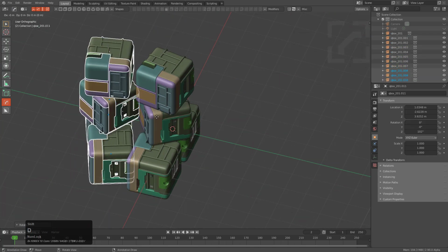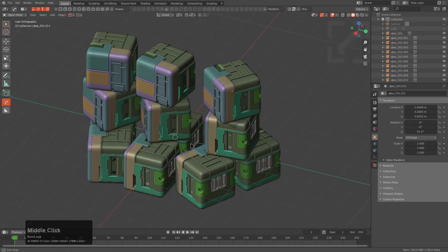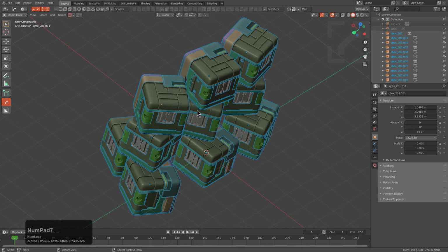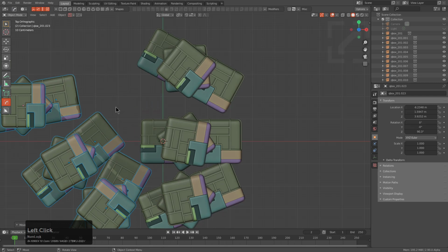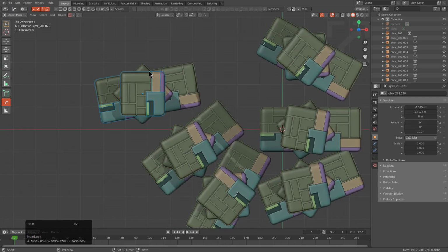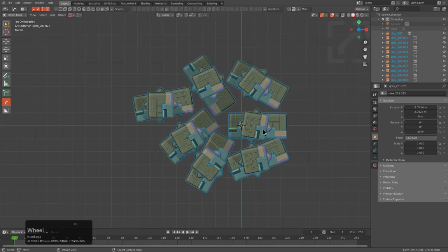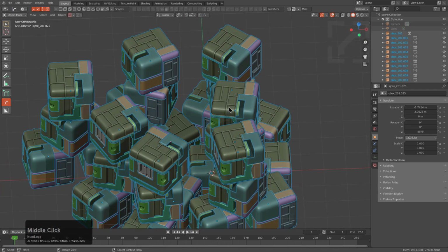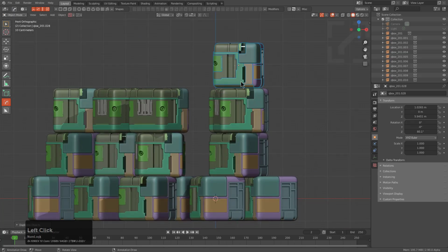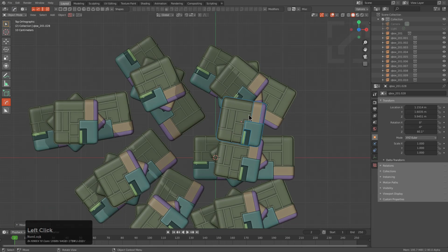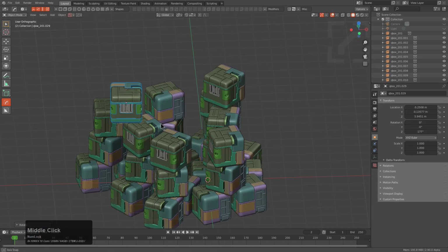And the best part about it is, because I was able to bring this over just as the object by collecting it via using HOPS Collect, which will also grab collection instances as well. So if your scene is built up of collection instances and you perform a collect, you'll also be able to collect those into a group instance as well to reuse those in other files. So if your file is built up out of group instances, we also care about ensuring that you get those to your destination with collect.